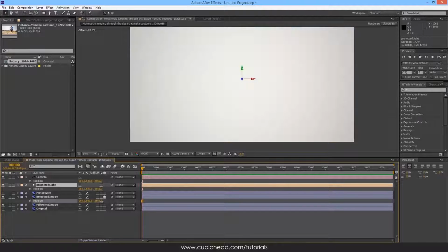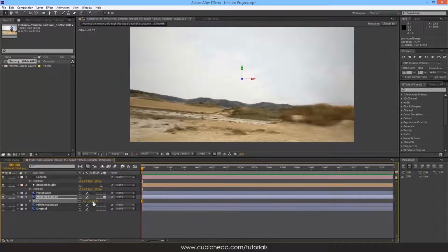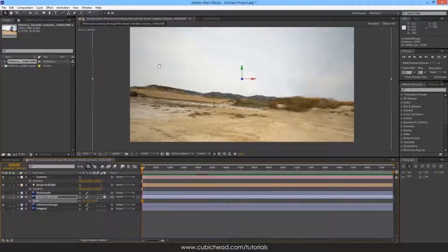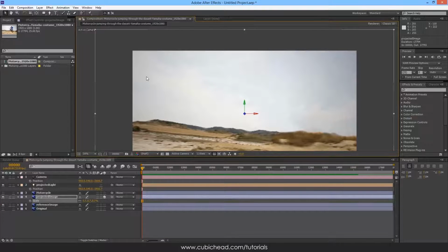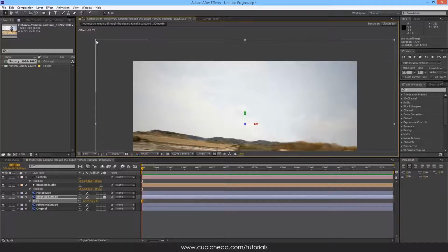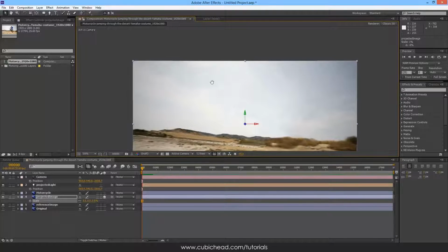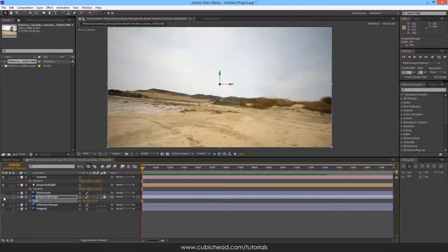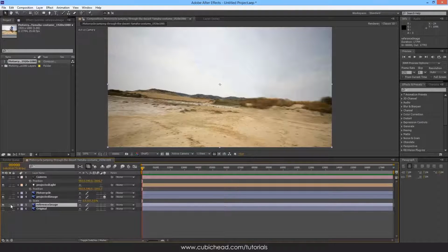Put this projected image a bit in front of the light, the projected light, and scale it down to about maybe 1 or maybe less, 0.7. And from here on I change the scale manually so it'll match the reference image. See, it almost matches. Now the 3D image and the 2D image are at the same place, so from now on I can use this reference image.